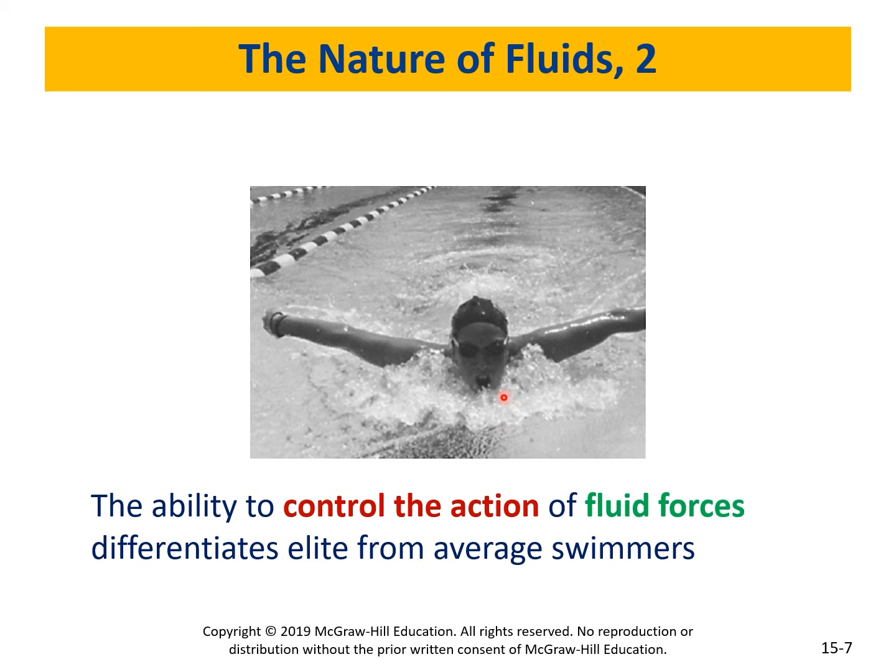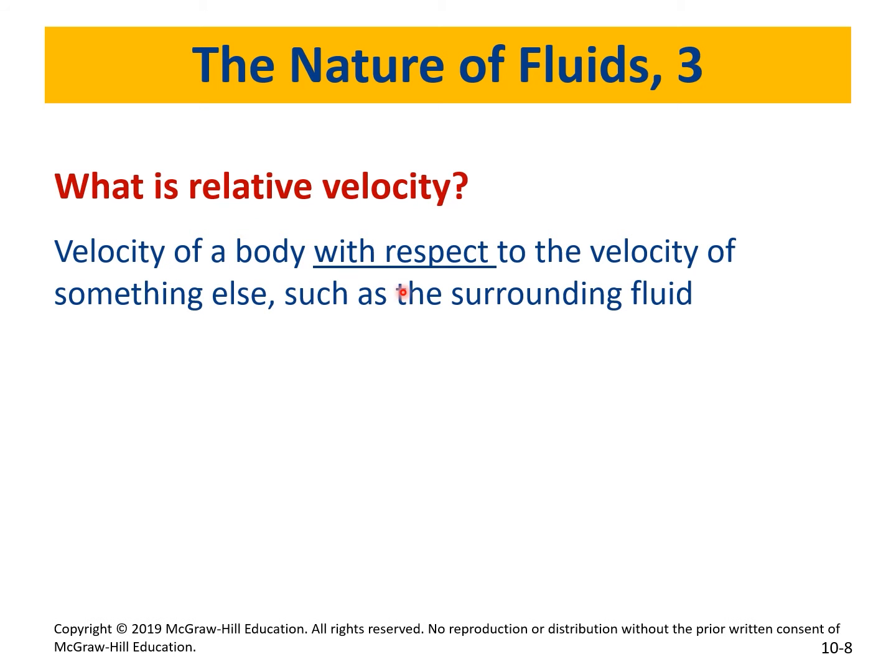You need to be able to identify your center of gravity and center of volume. Do you know the center of volume? We talked about center of gravity, center of mass. There's something called center of volume. The center of volume is something we need to identify because it affects the forces generated by fluids or liquid. Now let me show you what I mean by that. Before we start with the liquids, we have to make sure that we are on the same page when it comes to something called relative velocity, right?